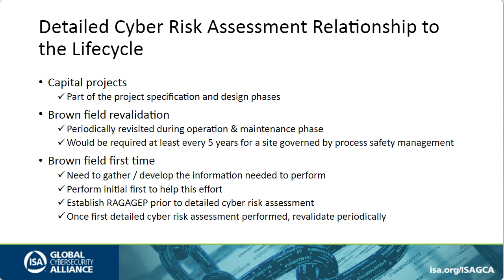You also want to make sure that you've documented your RAGAGEP prior to the detailed cyber risk assessment. Once you've done all that, then you actually will perform your first detailed cybersecurity risk assessment, and now you're into the life cycle just as if it were a greenfield kind of thing, and you will periodically revalidate that on the same kind of basis.